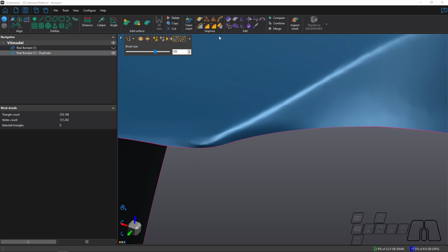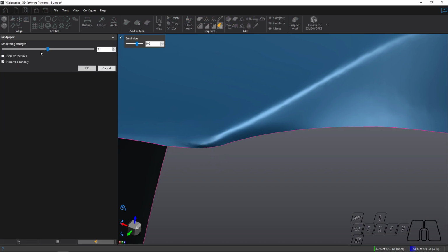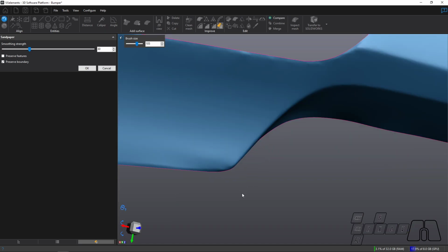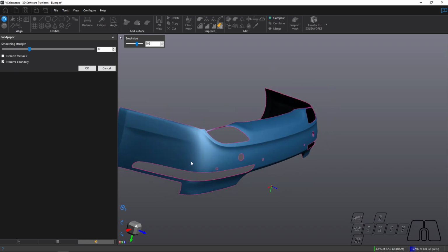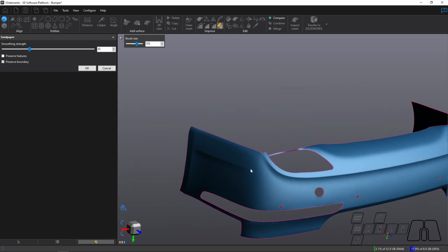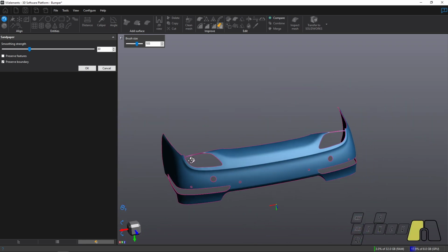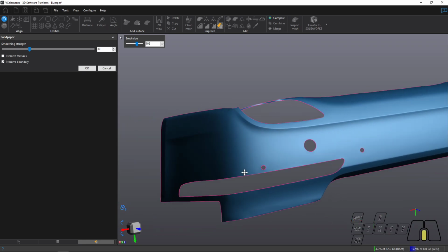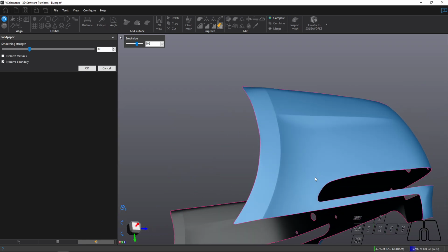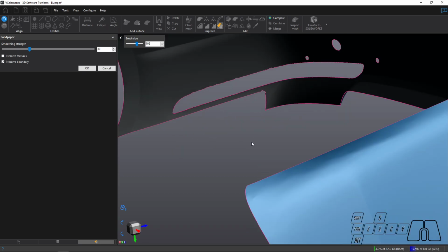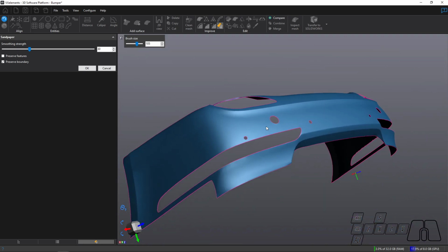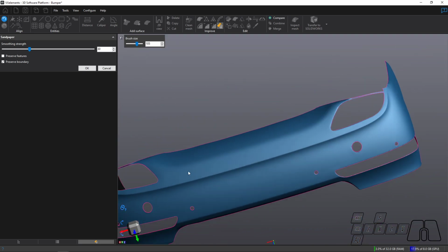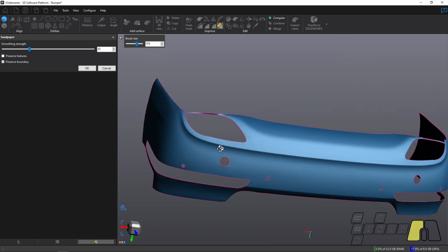But if this was scanned without bending between both sides, I could easily run a mirroring algorithm here, but it will really depend on how VxModel detects the symmetry plane and how well it does it. If not, I'll have to make the same cleanup on the other side. So let's try it out and see what happens.